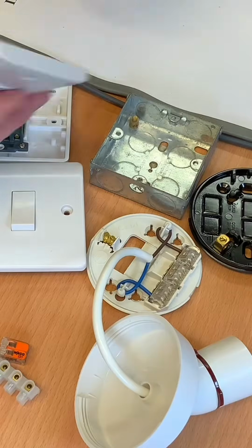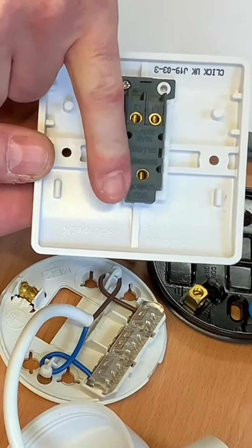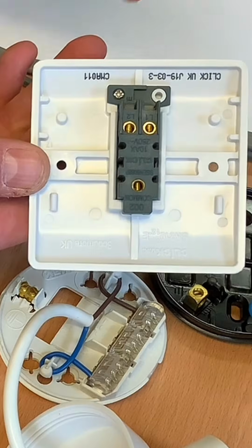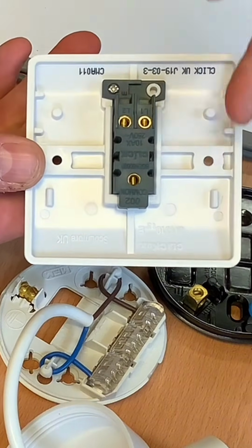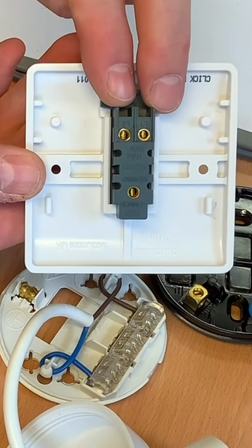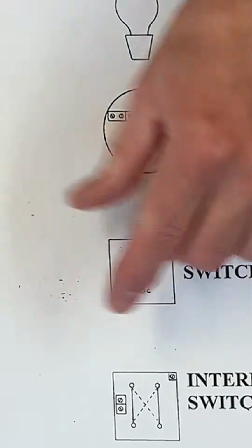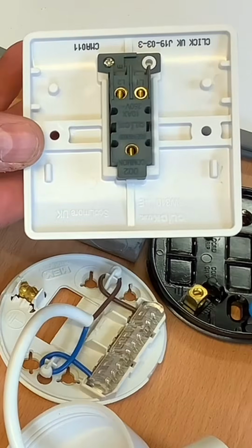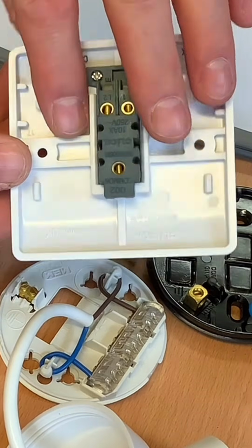We looked at the two-way switch in a previous video: common, L1 and L2, or terminals to that suit. Sometimes you've got L1, L2 and L3, but you've got a common, or one terminal on its own, and 2 other terminals. Okay, so that's there. So exactly the same, this diagram here will help you connect up a two-way switch.